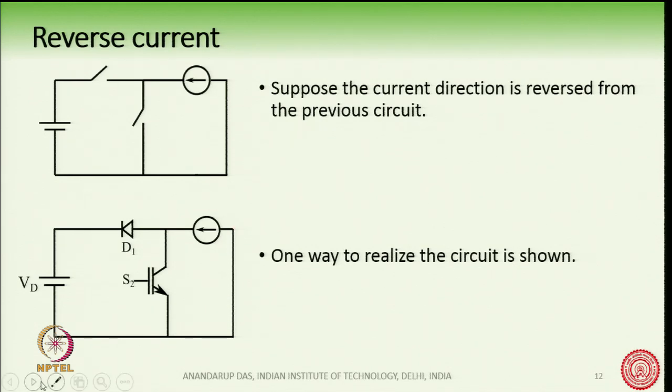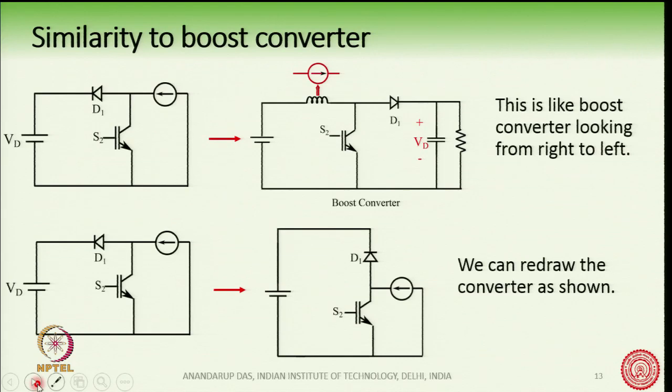So, this circuit, where the current direction is from right to left, is very similar to a boost converter, but you have to look from right to left. For example, this is a traditional boost converter with the voltage source and the load here. In a boost converter we have an inductor